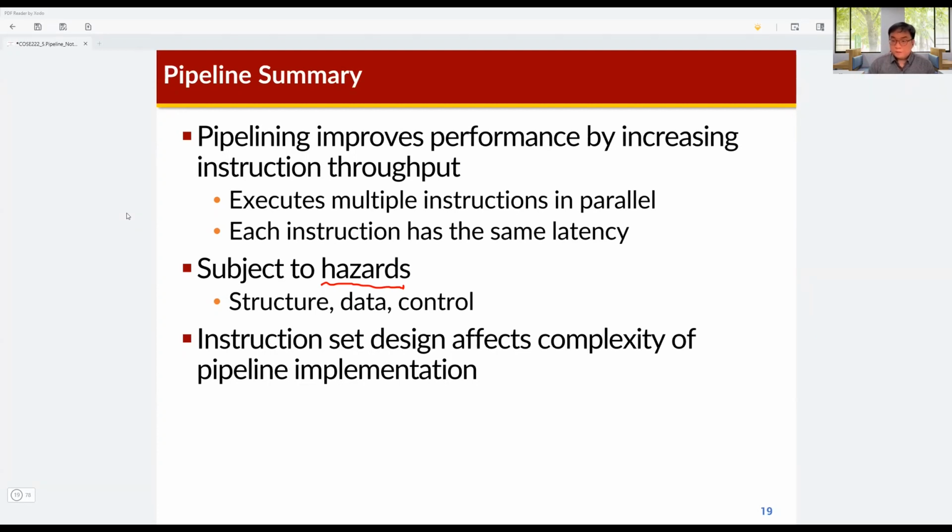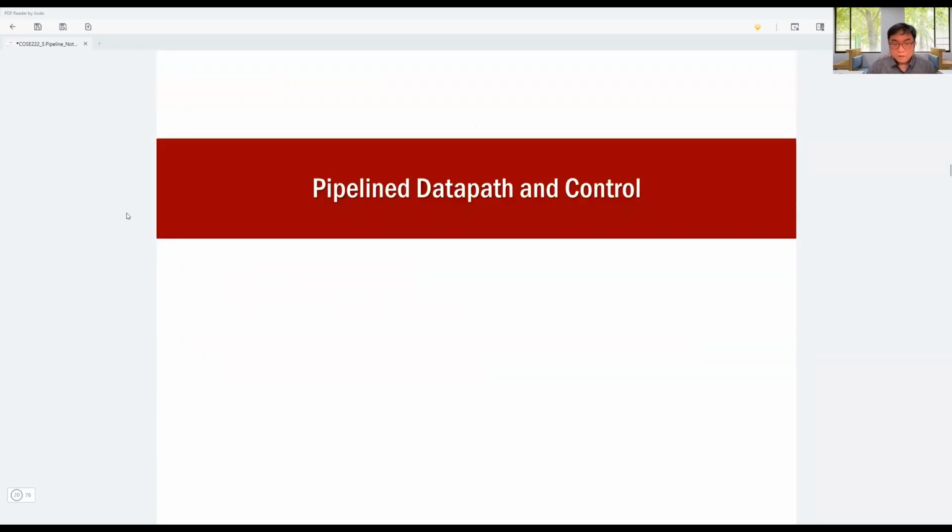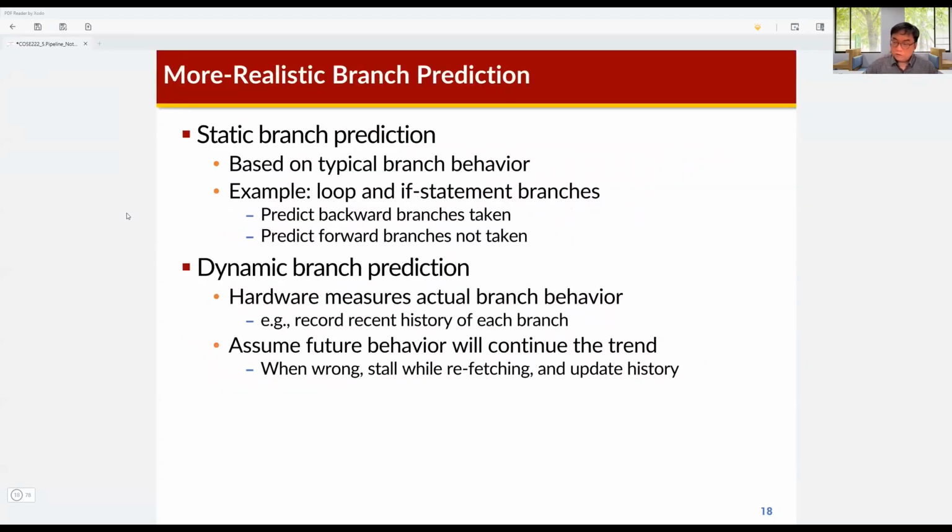Then we need to cancel the next instructions, and because of these branch instructions, clock cycles are wasted. This is the control hazard in the pipeline process. It's very important, so you need to understand why hazards happen in the pipeline processor, and what the reasons are, that means the sources of hazards.